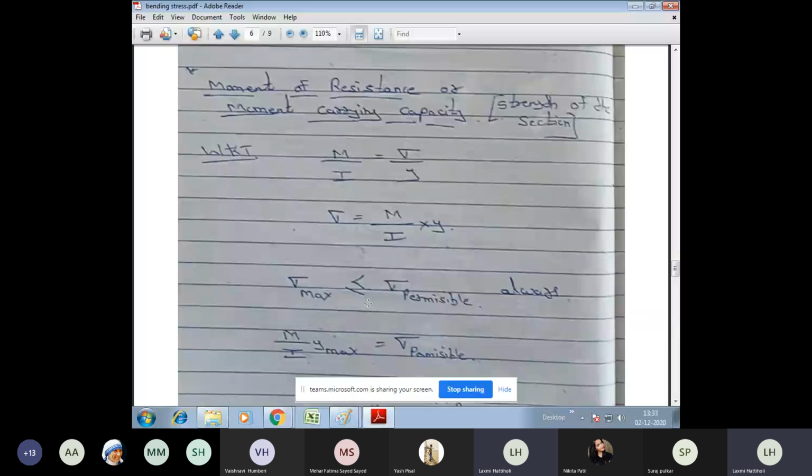While designing, you should never take that maximum load, that ultimate load of 100 kilonewton. You should always give some safer limit, or we can say a factor of safety. You have learned what a factor of safety is in the first module. By giving some factor of safety, I come across something known as the permissible limit. Of course, you can call it the elastic limit also.